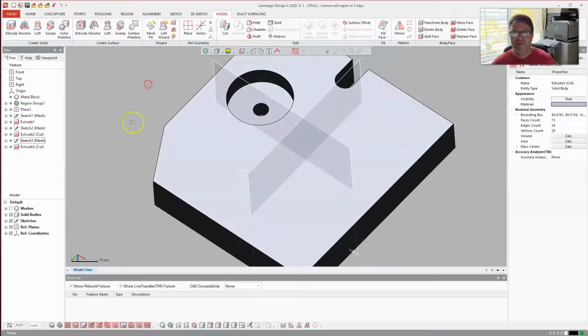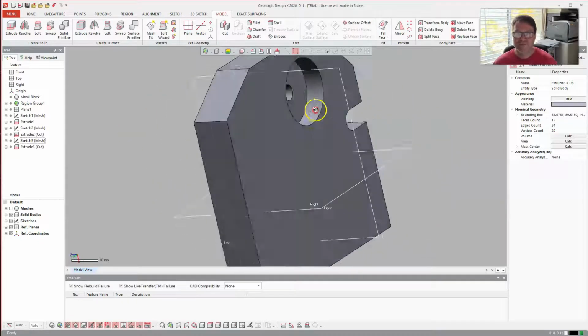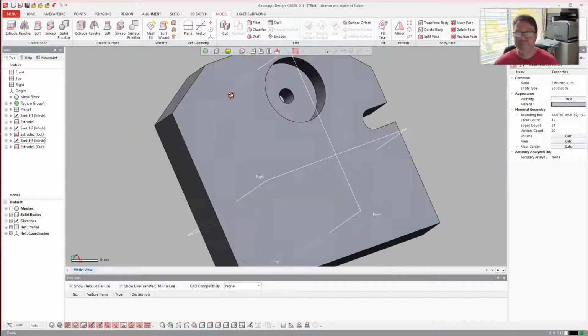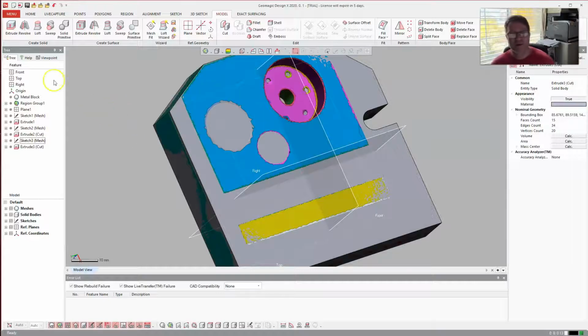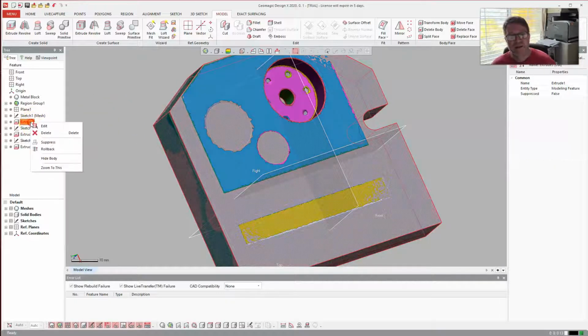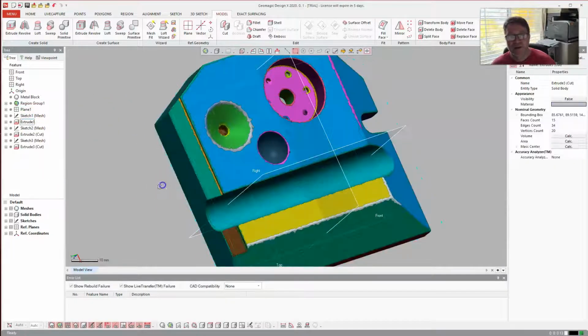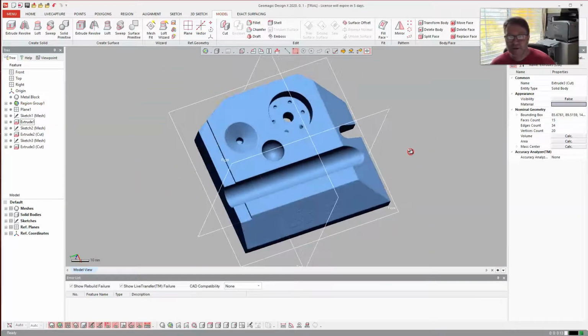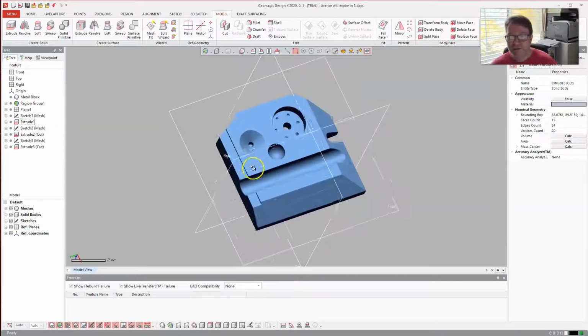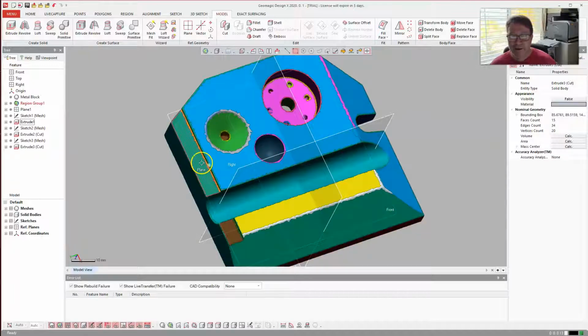Now I have actually the first shape complete. Remember, we're ignoring that little outer pattern feature. So Control 1, turn that back on. Now I want to hide our extrude 1 again, hide body. Which one do I want to work on right now? Let's do this plane right here because it goes all the way across.